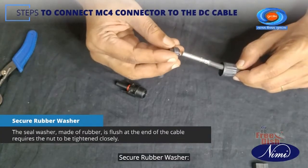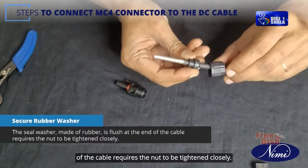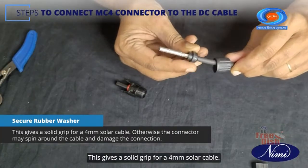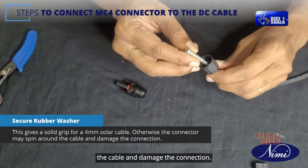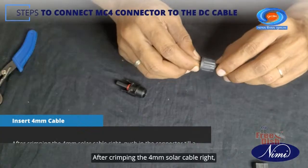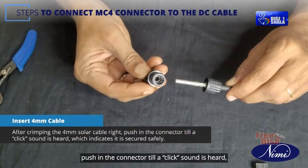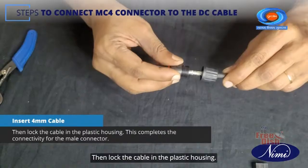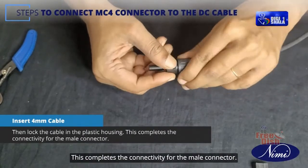Secure rubber washer. The seal washer, made of rubber, is flush at the end of the cable, and requires the nut to be tightened closely. This gives a solid grip for a 4 mm solar cable. Otherwise, the connector may spin around the cable and damage the connection. Insert 4 mm cable. After crimping the 4 mm solar cable right, push in the connector till a click sound is heard, which indicates it is secured safely. Then lock the cable in the plastic housing. This completes the connectivity for the male connector.